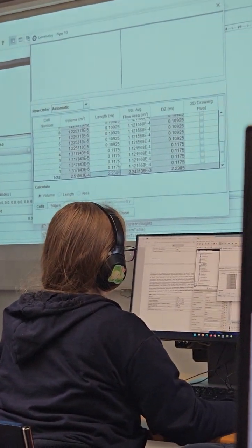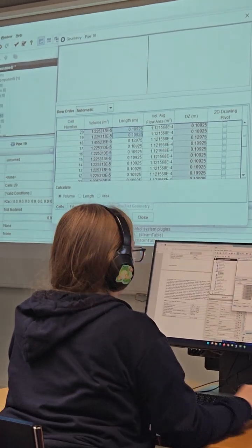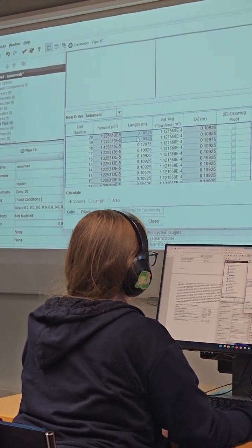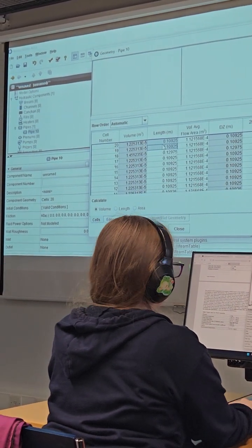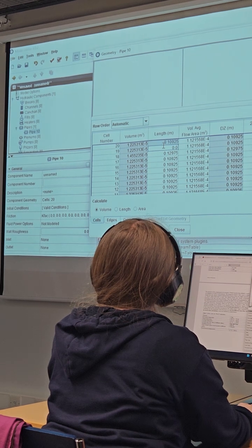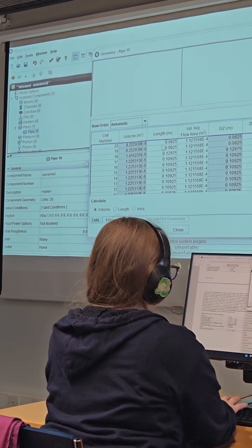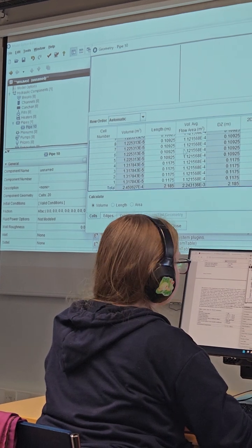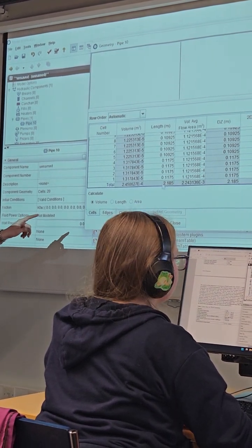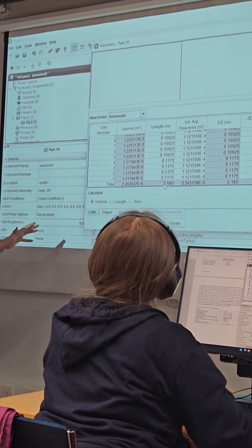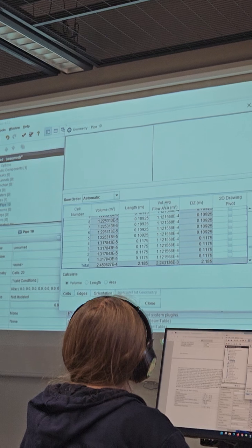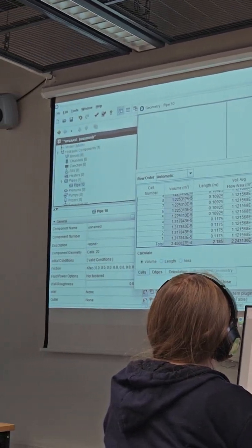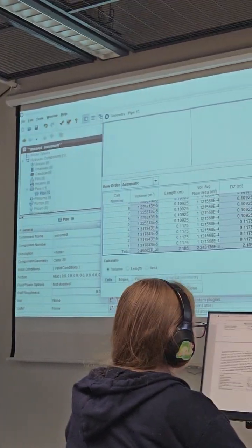It is 2.20, almost 24 meters. It should be shorter. So the other 2 cells, we need to reduce the size of these cells. So we just change it to 0.0825, these 2. So then if you go down, the total length of the tube remains the same as it was in the initial conditions in the table in the assignment instruction. Flow area and volume are calculated automatically.